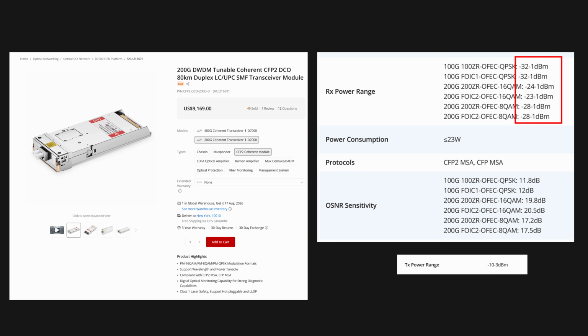When I look at the specs for a coherent long distance 200 gigabit fiber transceiver, the minimum receiver power falls right into this range. And this is no coincidence. You can see these transceivers have a few modulation options, including lower data rates, and usually more parallelized options with lower spectral efficiency per channel require non-linearly less power, just as in RF.